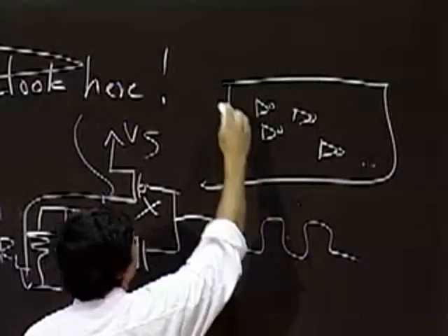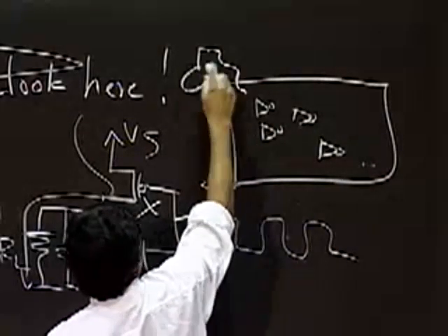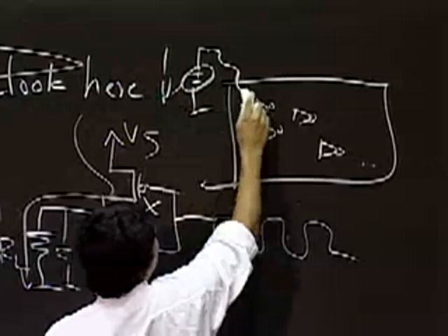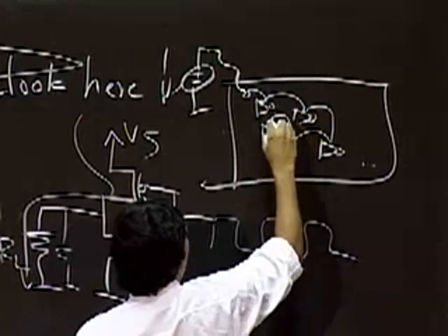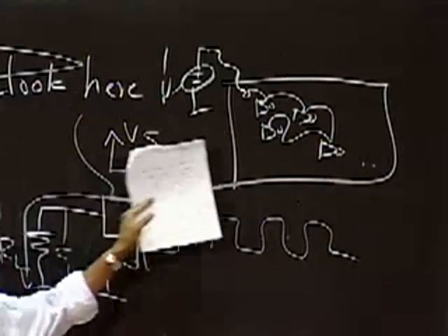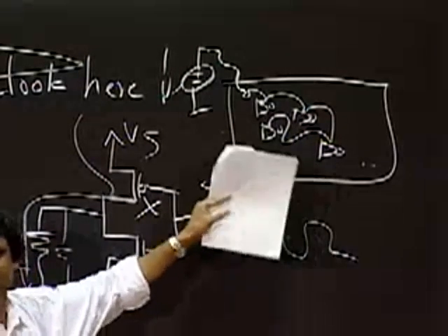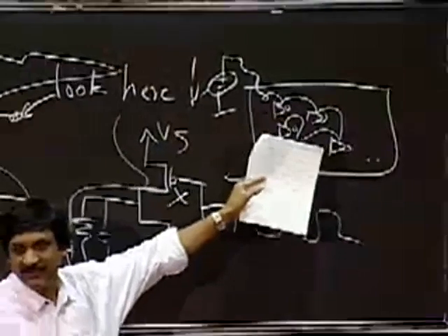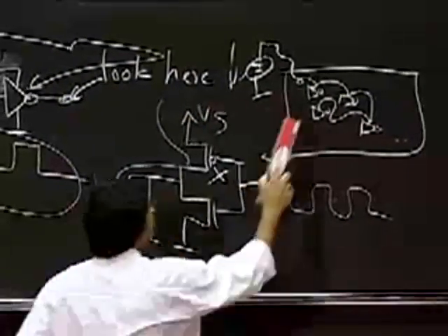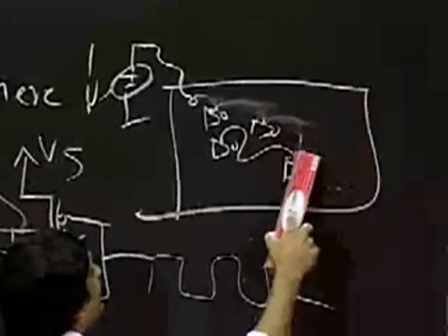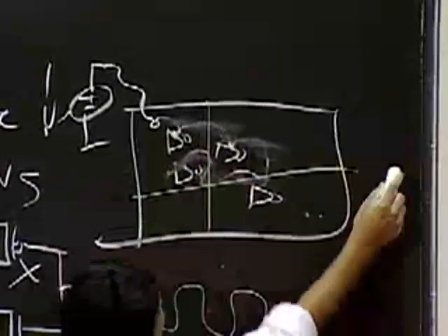What you do not do is bring in your power supply like this and then connect everything. You don't do that. That's the worst possible thing you can do, and it's an absolute disaster, for the reason just brought up. So instead, what you do is divide up the chip into, let's say, 4 quadrants.